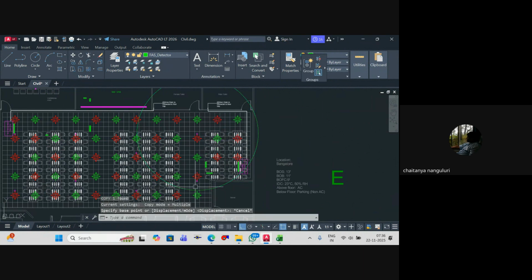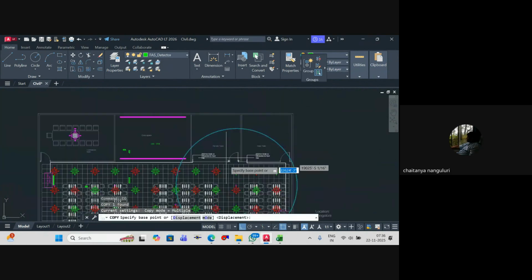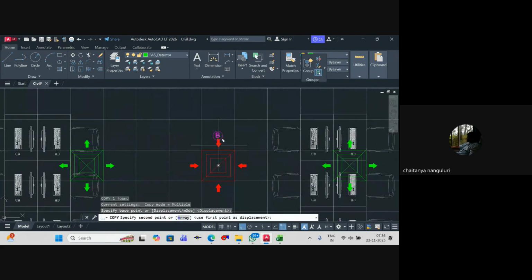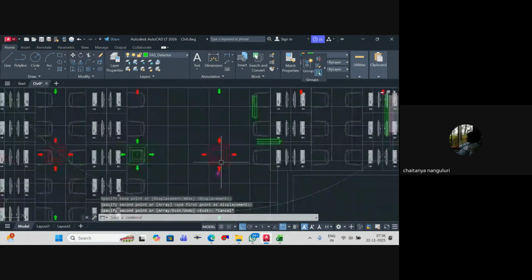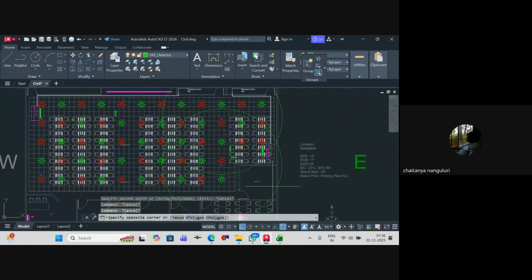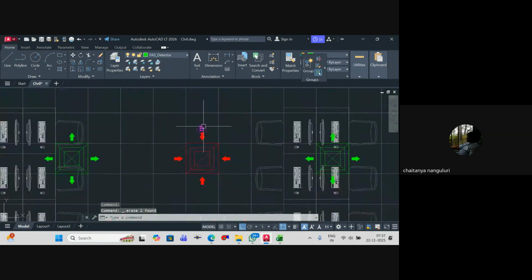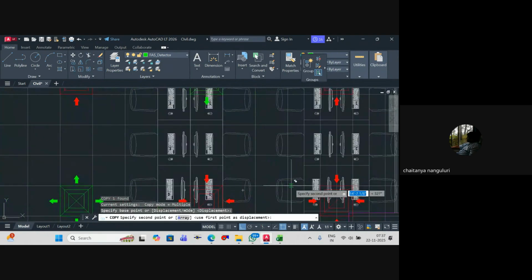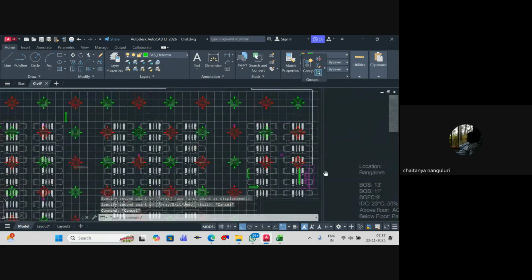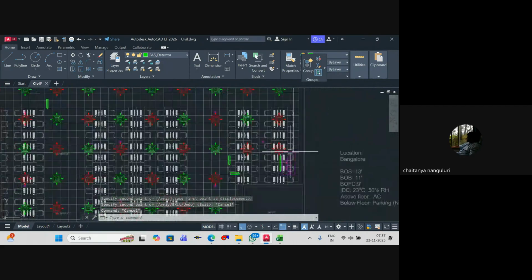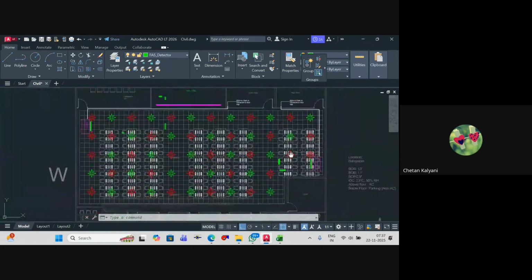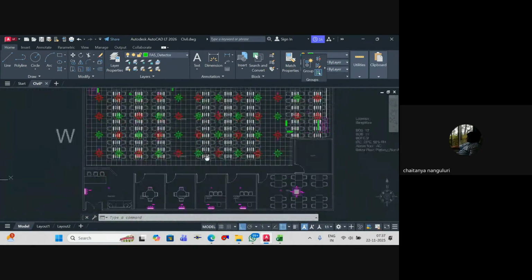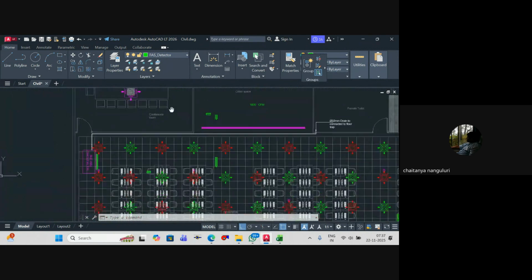This is covering this entire area. So this could be covered by this one, and within that 7.5 meters, it should reach. That's it. So you have it over here, something like that. So this is okay. Or safer, if we really want to be safe, you just place one more at this location because smoke travel in this corner might not be good. We'll place one at this location. Is this fine? So we have placed the detectors in all the spaces. Now, don't you think we have to do it in this conference room?